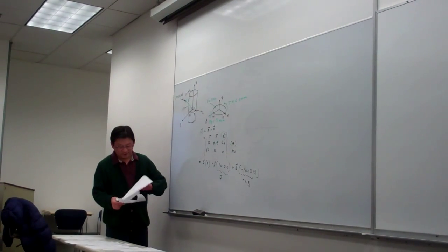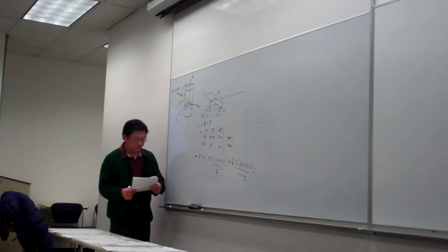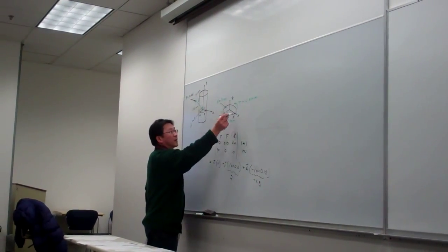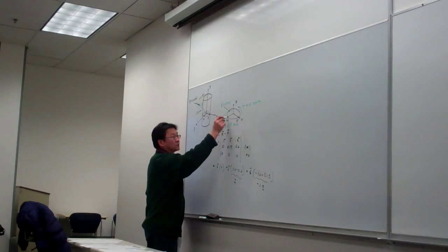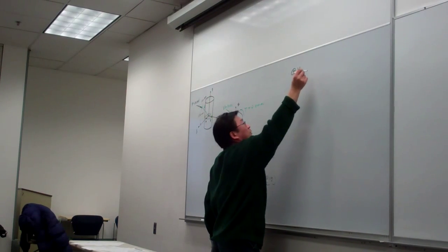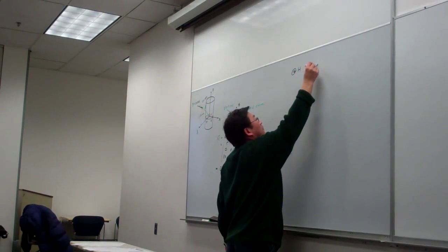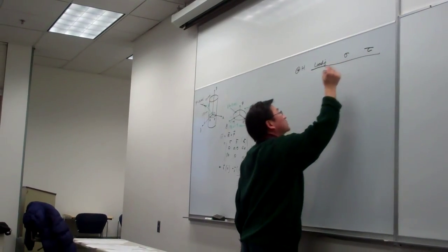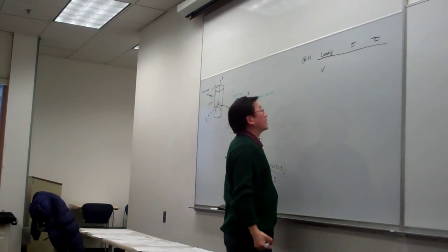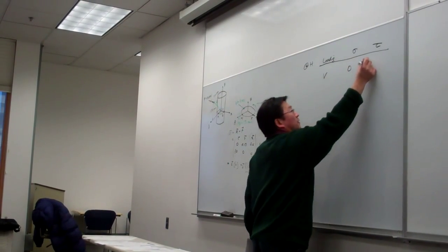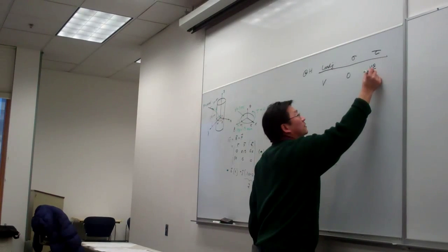So now with everything ready, we can proceed. So at the point K, you have calculated as a part of the homework. So right now we calculate H. At point H, we have the loading, and we have the normal stress and shear stress. In the loading, we have V. And V is 10, so here is 0, and this is VQ over IT.